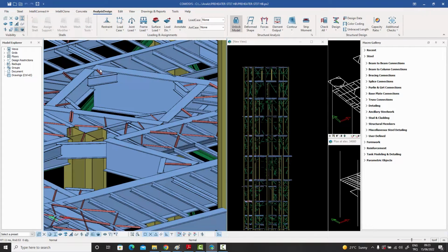And if you were to do a design according to those shear loads, you will get a very small number of bolts, maybe 3 or 4 bolts just to connect this huge beam. But this is also a practice which is avoided in steel structures. You would typically want this beam to be about half full of bolts or something like that. So these are the contradictions which we face: if we just convert the forces from the analysis into this beam and design directly according to those forces, you end up with something which you don't like. So this is something I just wanted to mention at the beginning.